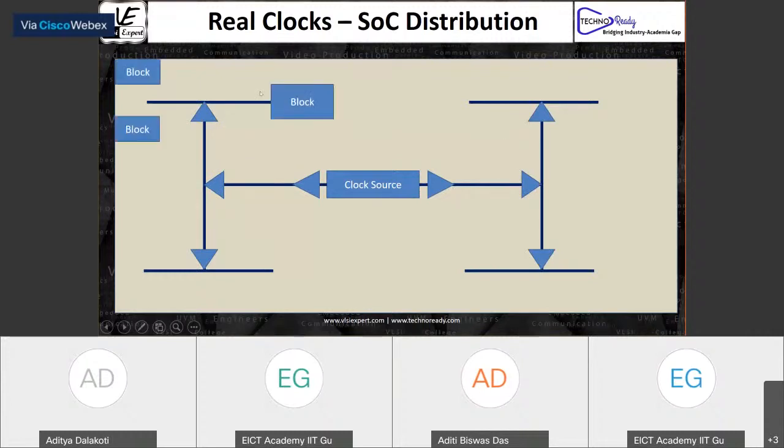Then the clock tree with the matched skew, as long as the distribution is matched, your skew would be matched, reaches some blocks. In the blocks, you may continue with this symmetric distribution, or you may just short the blocks using different approaches of clock tree. There is a skew buildup possibly wherever there is a mismatch. So as long as you don't create an H-like symmetric distribution or some other symmetric distribution, you will have mismatches and the skew will build up, which you need to account for.